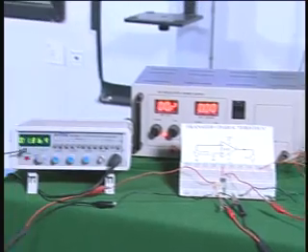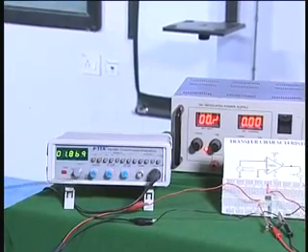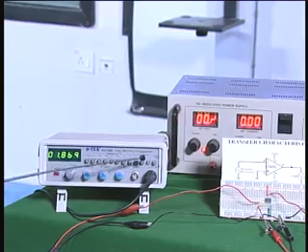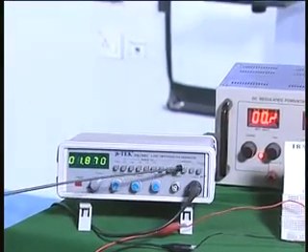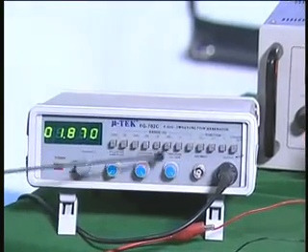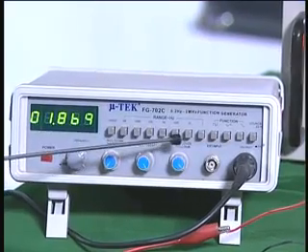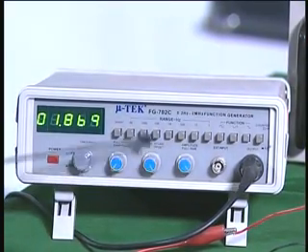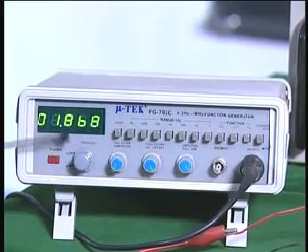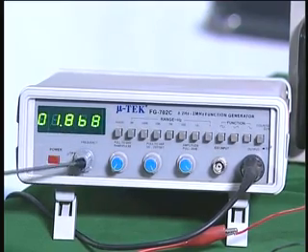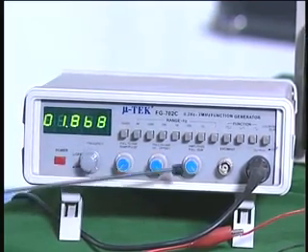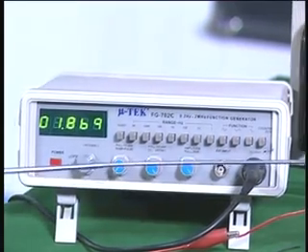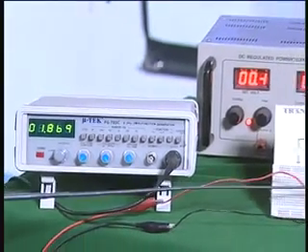And this is the signal generator, the sine wave oscillator, basically a function generator which can generate all types of waveforms, sine, triangular, square, etc., and we have put it in sine, and these buttons are for choosing different frequencies. I have chosen something around 1 kilohertz, and therefore it is about 1.8 now. Using this knob I can vary the frequency, using this knob I can vary the amplitude, and the output is connected at the input of the operational amplifier.